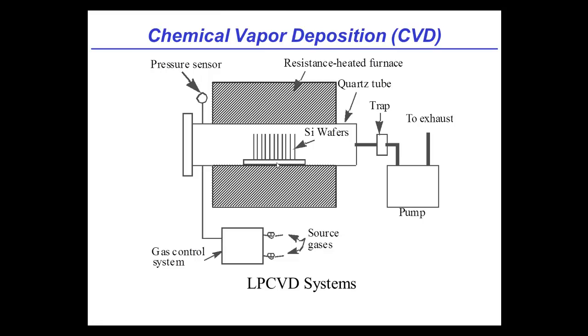That's right. And then the second reason to run at low pressures is that the films go down more smoothly, so you can actually improve the quality of the film that's deposited. Yeah, that's right. Both of those points get to a common theme that we touch on from time to time, which is really the beauty of modern semiconductor fabrication processes. We're really talking about atomic control over the deposition, and that's exactly what this lets you do.